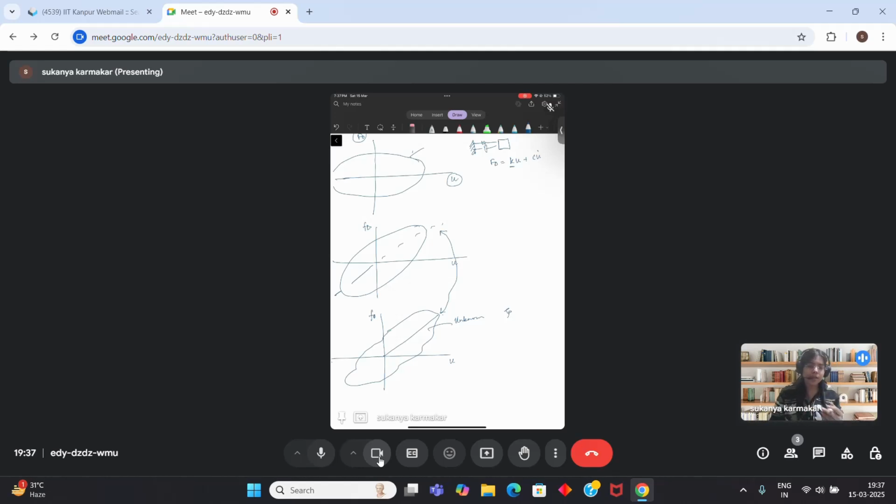So when we are comparing the two systems, we are equating the energy dissipated. So basically what we are doing, we are equating this area with respect to this area to calculate the equivalent zeta for this unknown system. This is the entire idea of the equivalent viscous damping. That is, for this unknown system, what will be the value of viscous damping? So this is very clear. Okay.